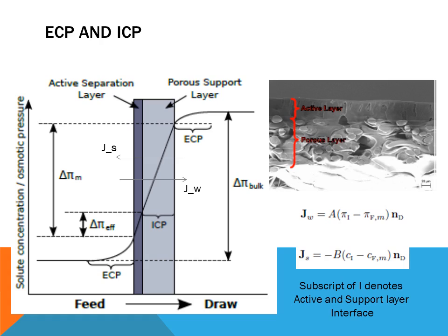Okay, so now we get into the actual membrane. The kind of membrane used for forward osmosis, if you look in the upper right corner, has a thin active layer which basically just allows water convection through it and ideally rejects salt. If the pressure gradient is very high, then you can get backflow through those channels. You can also get some sort of capillary effect where salt just randomly passes through it. You could also have defects in the membrane that will allow salt passage.